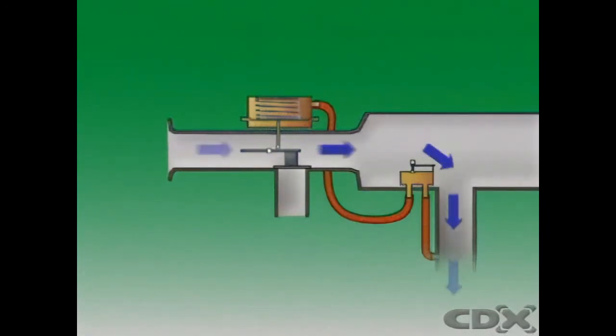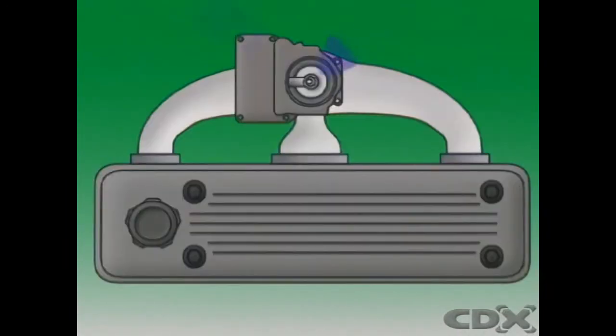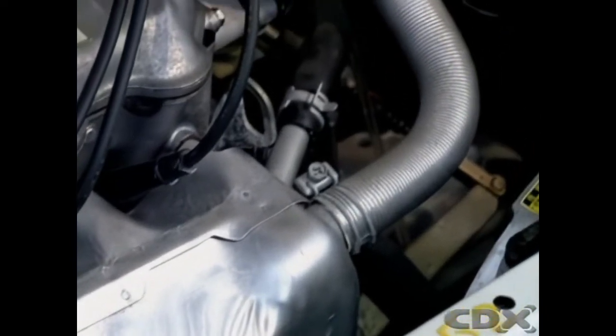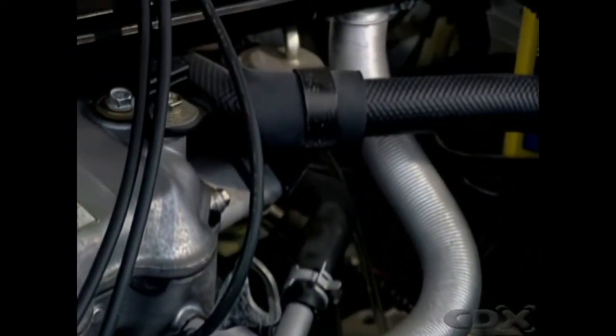Normally the air entering the air cleaner is cold. Cooler air is more dense, that is, it contains more oxygen, and that should help the fuel burn more efficiently. But fuel doesn't vaporize very well in cold air. Since an enormous amount of heat passes through the exhaust manifold, many carburetted engines capture some of it with a shroud around the exhaust manifold. This heats the incoming air to improve fuel vaporization. This heated air then enters the air cleaner.